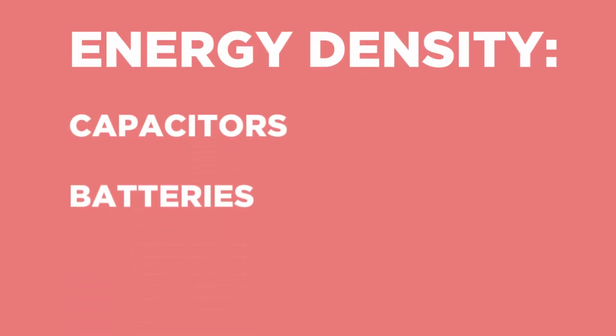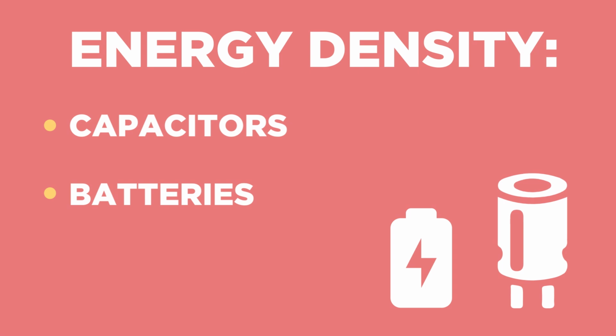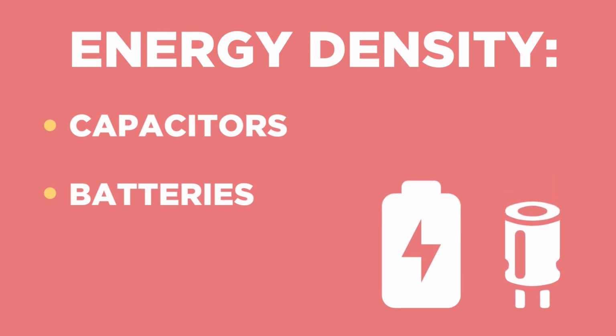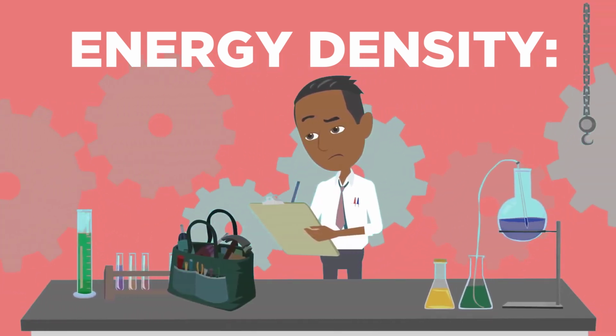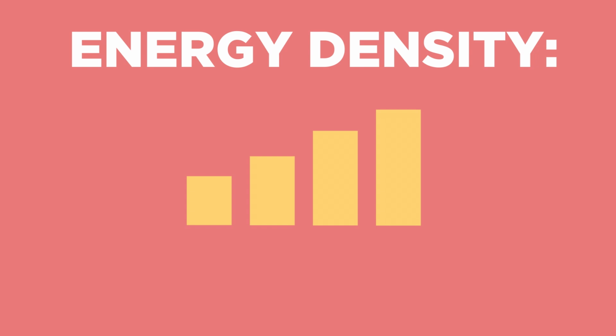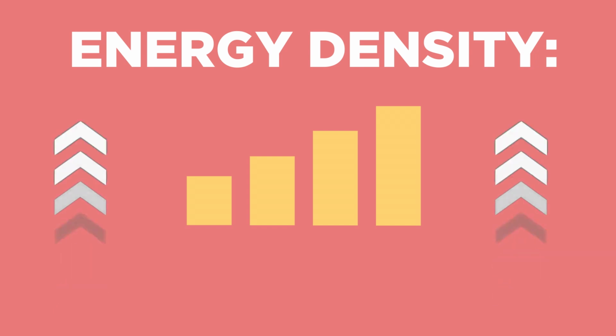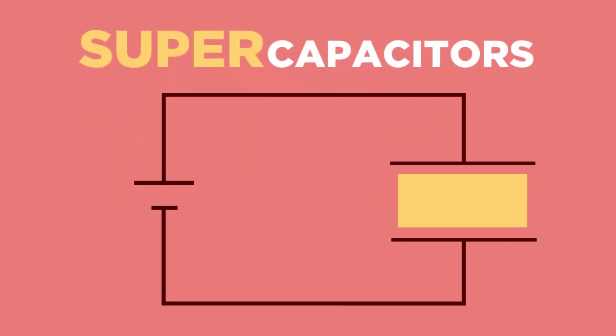The main disadvantage of such devices is the low energy density, especially compared to batteries. They can charge and discharge way faster, but the amount of energy that they can store with respect to their volume is really low. However, developments and discoveries in the land of capacitance brought to new ways of generating and storing energy in an electric field, which increased the energy density of these devices. The reached values were incredibly high compared to traditional capacitors, and for this reason they needed a fancy name: supercapacitors. In a supercapacitor, there is no dielectric between plates. Rather, there is an electrolyte and a thin insulator such as cardboard or paper.